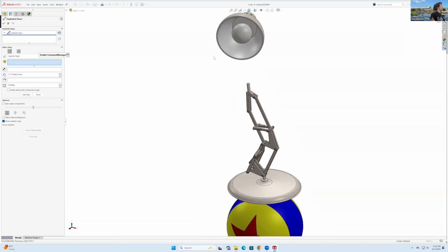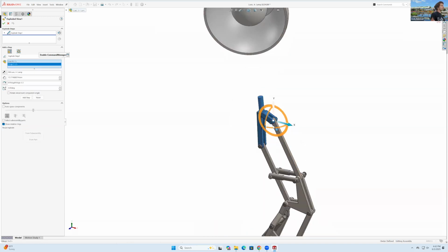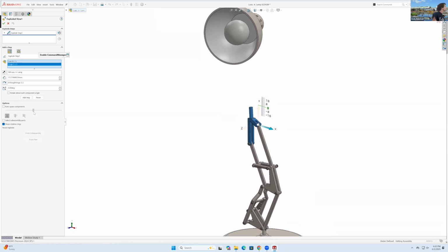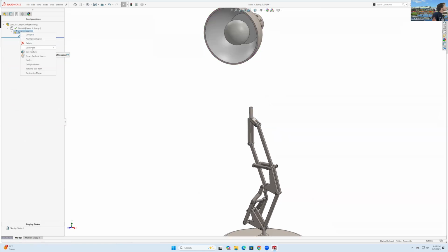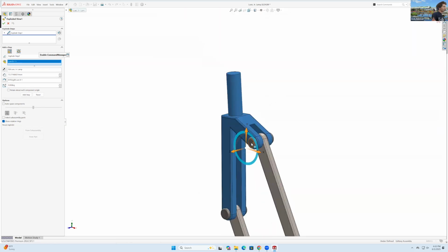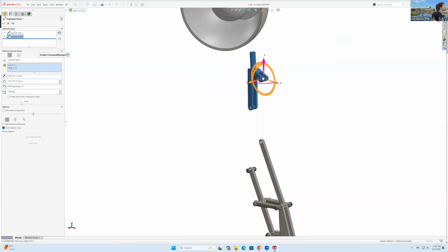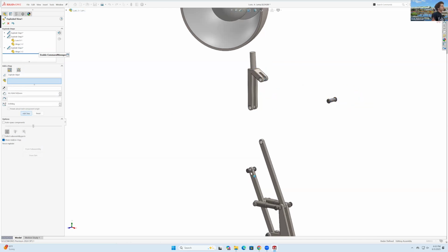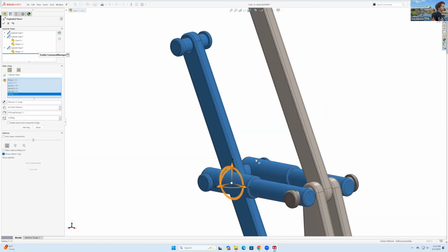I'm gonna start again. So step 2, I'll click on these two right here, and I'll make it go... why is it only constraining it? Hold on. Edit feature. Yeah, sometimes I get a little too excited. There we go. And SolidWorks starts complaining. I'll say done. Then I click on that guy, I move it forwards, done. Then this guy, that guy, all of these different parts.